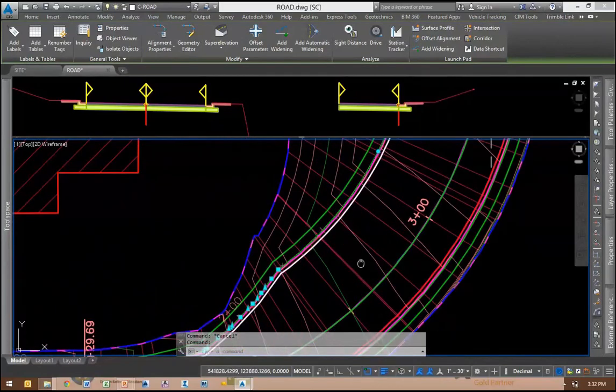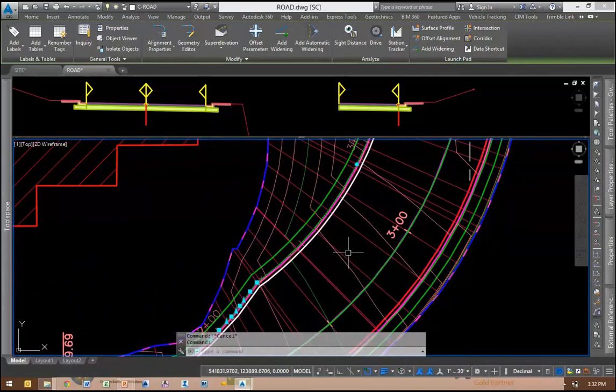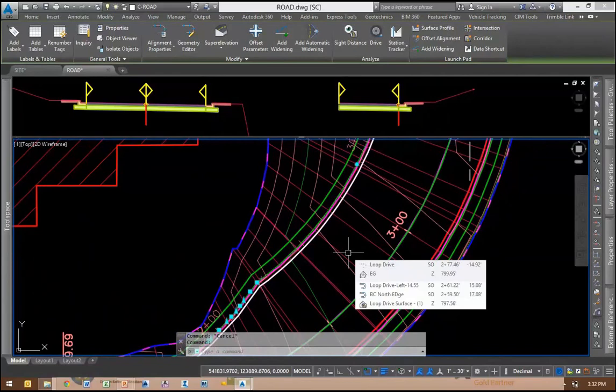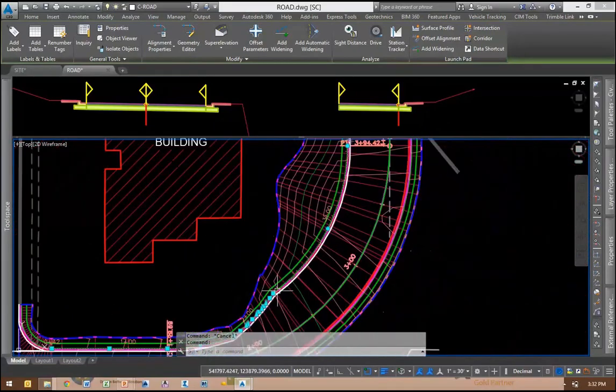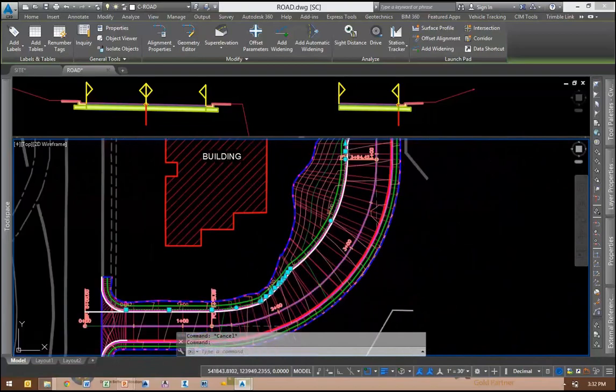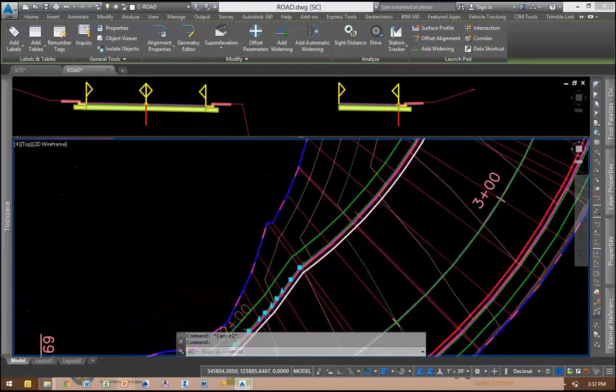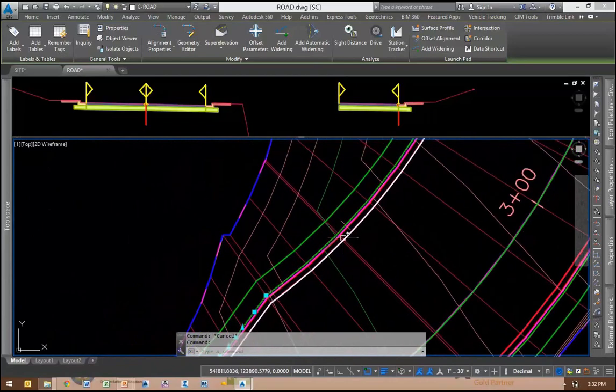Yeah. So those of you familiar with corridors, how many people use corridors on a regular basis? Okay. We understand what feature lines are in corridors. There's no curves in a corridor, is there? It's all chords along curves. Civil 3D is actually smart enough in this way that it actually gives you a curve along curves. It's kind of a nice feature there. The feature line, if we extracted that, right, we'd get a whole bunch of little chords.